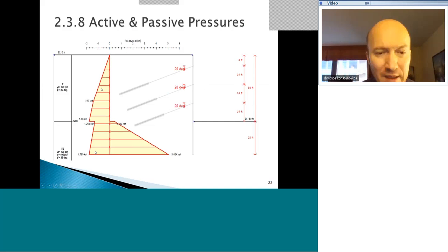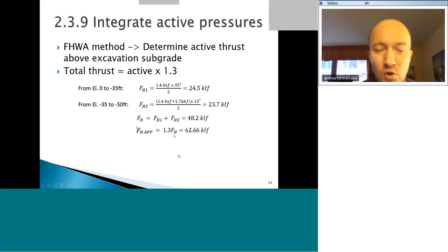Now, some engineers use active earth pressure diagrams for multiple supports. If you have very conservative soil properties, you can be fine, but you have to look into all stages, and it's theoretically inconsistent if you're doing that. So that's what the active earth pressures look like.